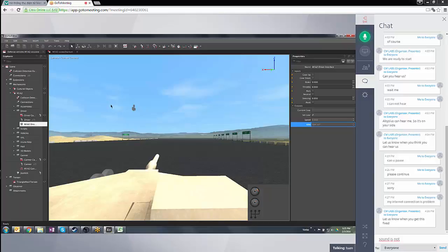Does the 3D model have impact on the simulation mechanism? Well, you do need to have a model that is properly articulated. So in your model, you need to have put proper joints to be able to move things like the wheels, the sprockets, the turret, the cannon. So all of these elements in the 3D model need to have been identified as elements that have joints, meaning that they'll be able to move during the simulation.